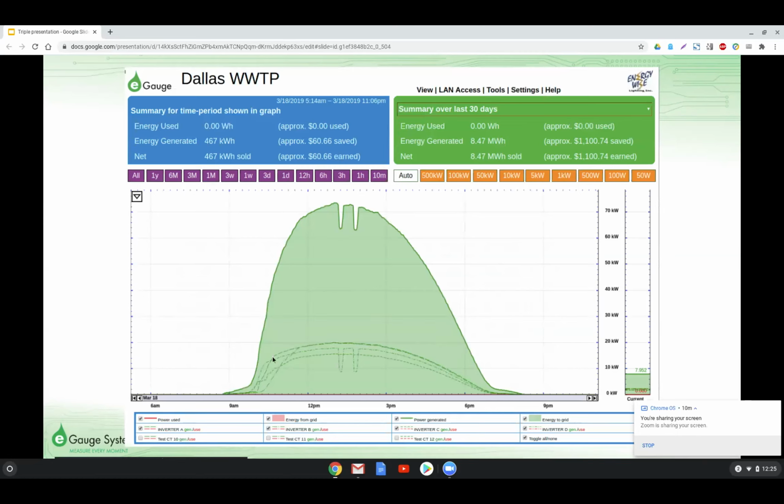You can see here, same type of thing, multiple inverters, all very similar. You can tell with this section here that the array is rather large, and certain inverters are going to get sun earlier, and certain are going to catch that peak a little bit later, but they all max out at the same. And now you can actually delve in by just choosing which inverter you want to look at in this register area down below and see what exactly is causing this dip. Every time you have these dips, you're changing the ROI of that system. So you want to make sure you stay on top of those.